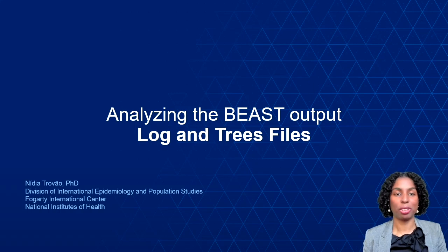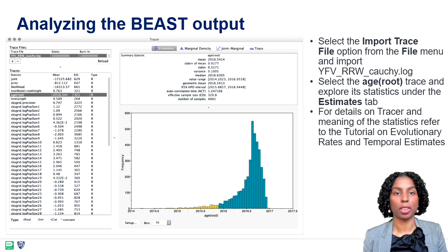In this session, we will analyze the BEAST output log and trees files. To analyze the BEAST results, we are going to use the program Tracer. Select the Import Trace File option from the File menu and select the log file from the previous section, or drag and drop the log file into the Traces window.